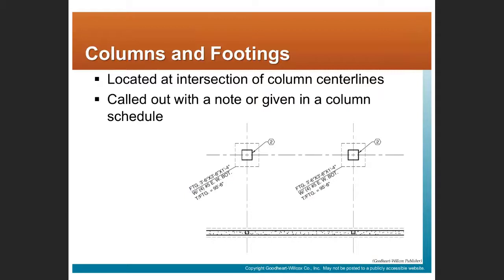Again, we typically don't have columns in a residential building, but we'll have columns in a commercial building. And again, those columns have footings. The footing of the column is generally speaking going to be wider than the foundation footing because that column is carrying a heavier load.